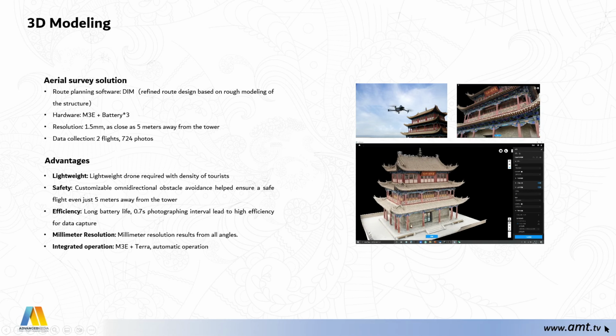So I used 3 batteries with the drone, with the Mavic 3E, of course, because in the surveying methods I will need to use the Mavic 3 Enterprise. So I used 3 batteries only. It took 2 flights to cover all of the area and 724 photos.